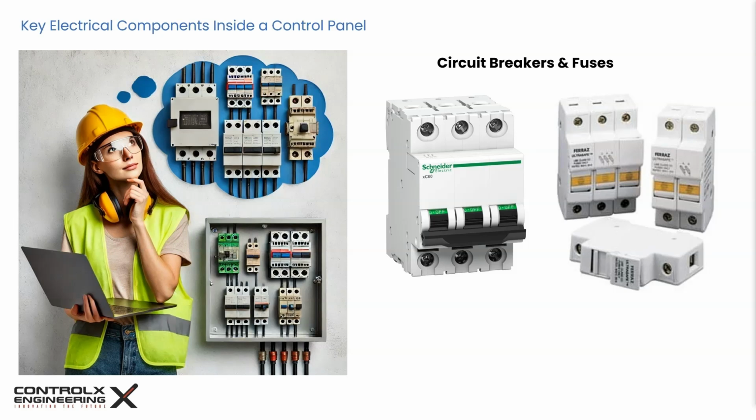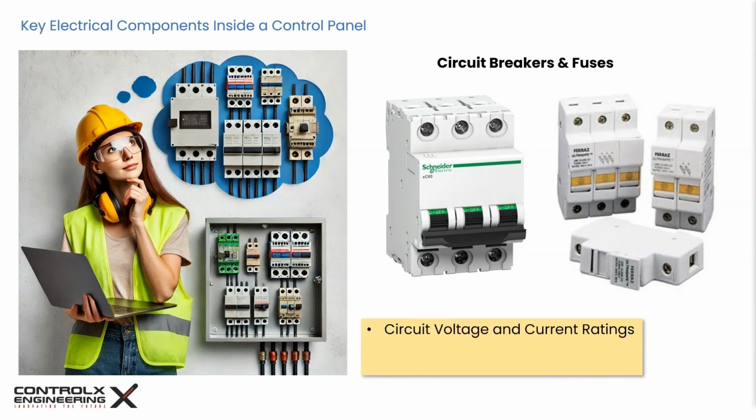When selecting fuses and breakers, some of the key factors to consider are circuit voltage and current ratings. Ensure that the device matches the voltage and current requirements of the circuit. Interrupting capacity. Choose one that can safely handle the maximum fault current expected. And response time. We need to select the right device based on the speed required to protect your device. Faster for sensitive equipment.